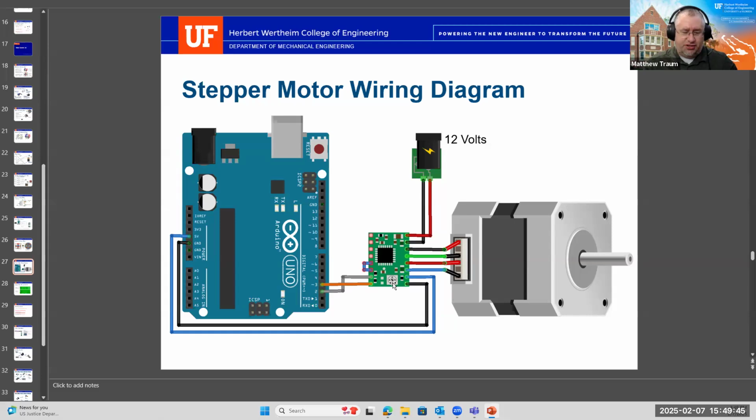And so every time you send a pulse, that causes the motor to take one step. And whether you've got the direction at the high voltage or the low voltage determines whether your stepper motor is turning clockwise or counterclockwise. So that's what you send from these output pins. All of the logic to convert that into how the stepper motor moves is done in the motor driver, and then the stepper motor, if you've programmed it and wired it correctly, will respond accordingly.